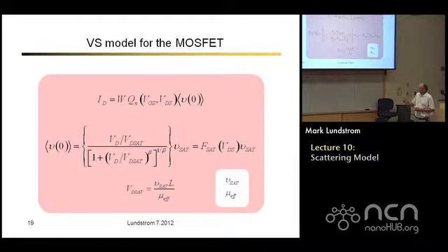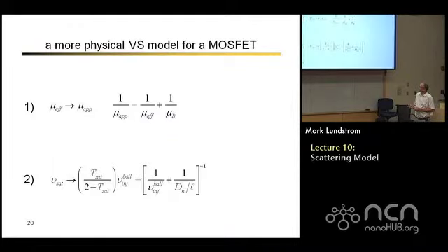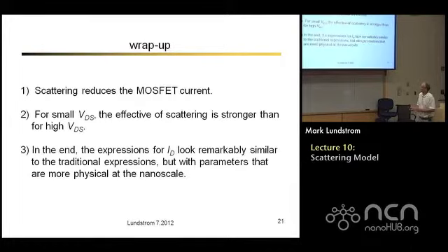And now we understand a little more what we're doing: these two key parameters here are really not physical at these length dimensions. So what we have to do is replace those two parameters by the appropriate parameters for nanoscale MOSFETs. Once we make that replacement, then the rest of that virtual source model works just fine. And we can treat nanoscale devices.